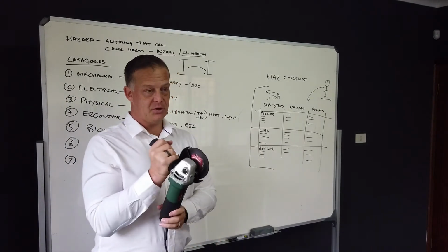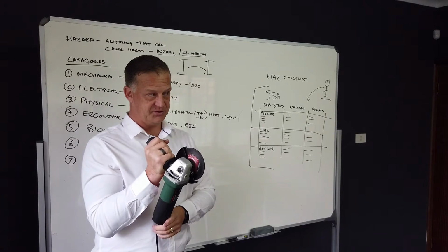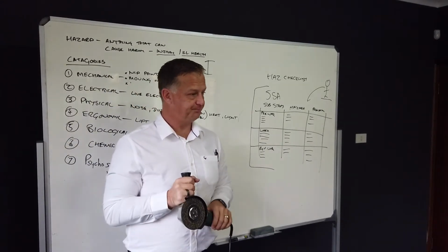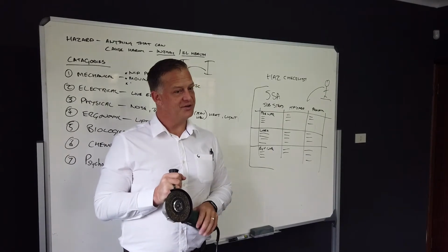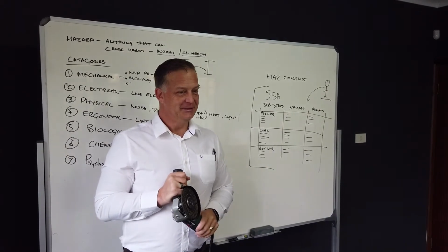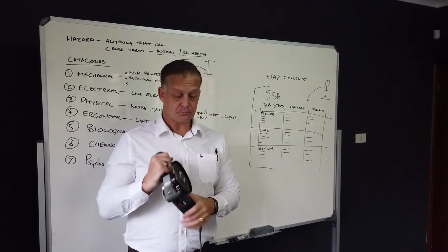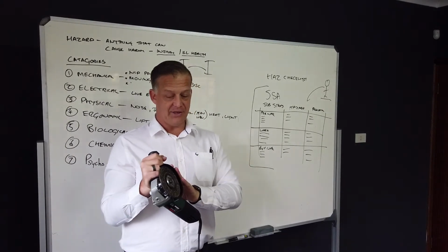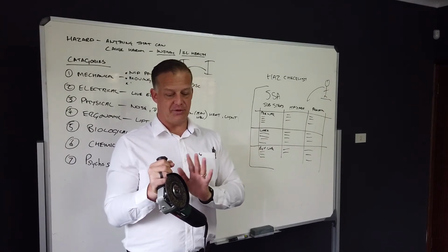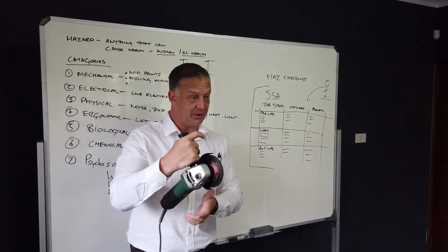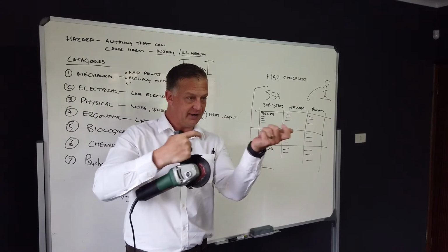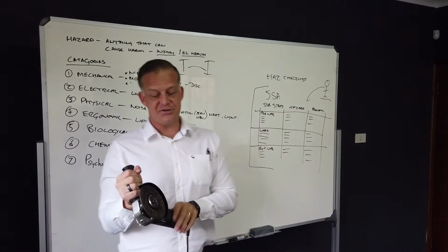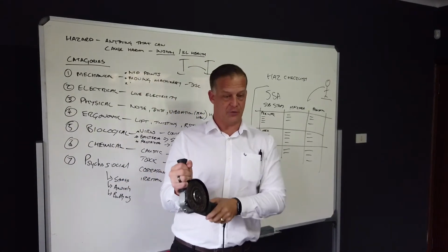Also, do you think I'm going to need personal protective equipment for this? Okay, what PPE, if I'm going to be using this, what PPE do you think I should wear? Gloves. Why do you think I should wear gloves? To protect your hands. Okay, so that's a good thing, but also what you need to be aware of as well, the gloves can protect you. Now, we can debate whether it's good to wear gloves with this, but also just remember, like with a hand drill, sometimes if you're wearing gloves and you're drilling, that glove can get caught on the drill bit as well. So yes, you could wear gloves because you're going to be away from the grind disc.